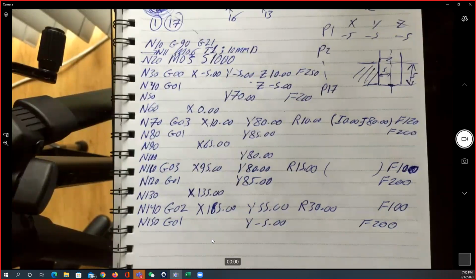I will just give you a brief of his theory. He said that the velocity multiplied by the time of the machining to the power n is equal to a constant. That means higher velocity or high cutting speed will reduce the time, and vice versa.